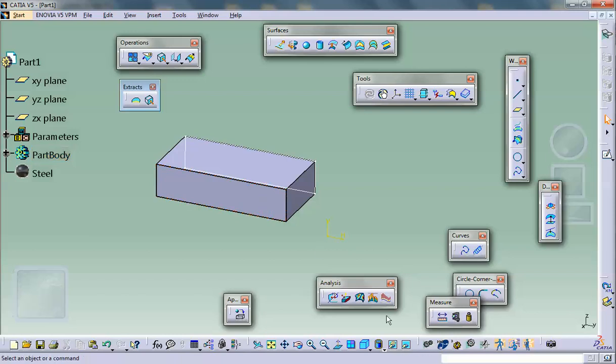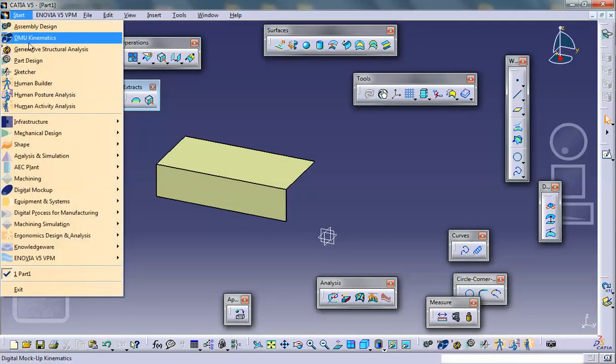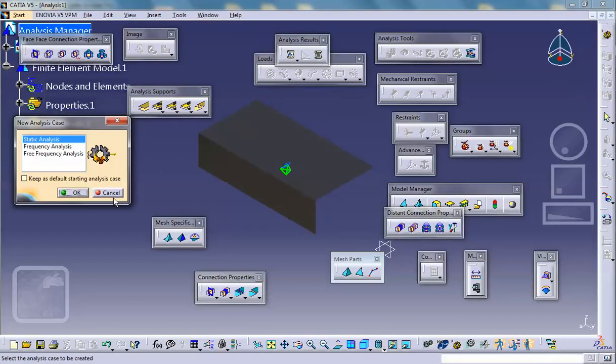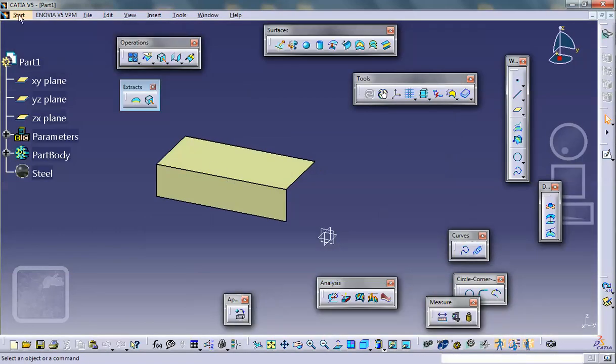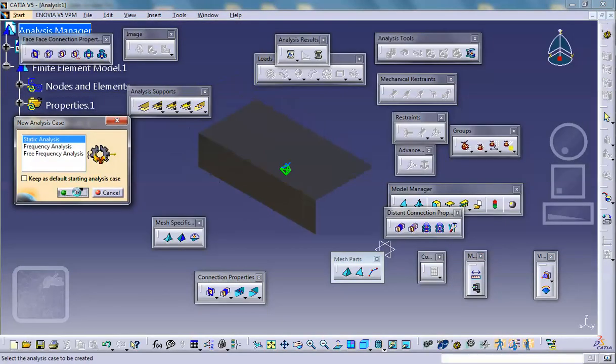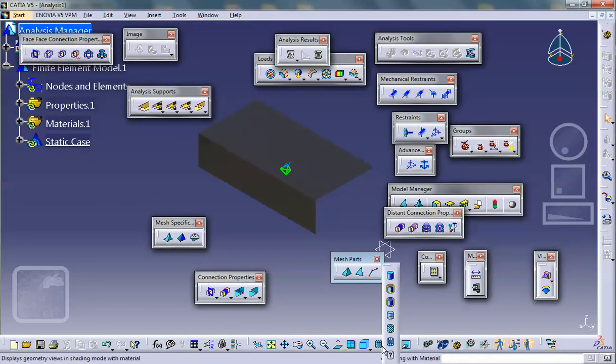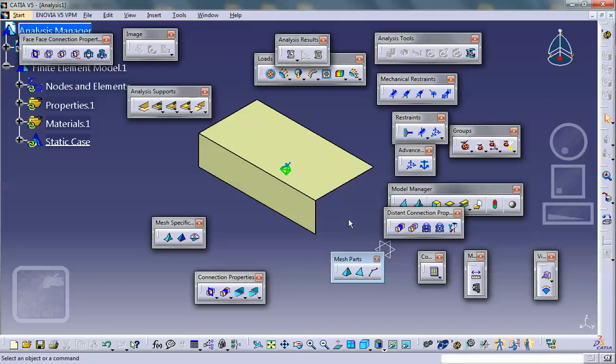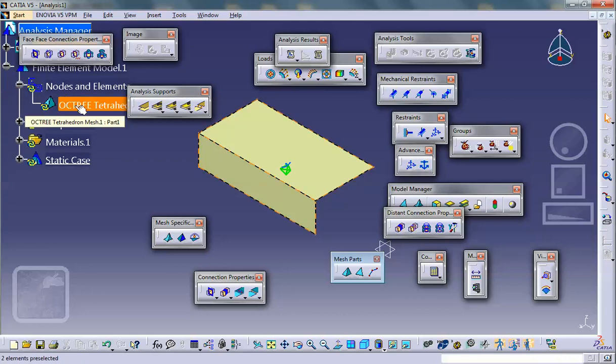Immediately, you see that the box that's in hiding is meshed with solid elements. Here are solid elements. We don't want these elements because we're supposed to do this problem with shell elements. And also keep in mind that if, on a test, you are asked to use the best element to do this problem, and you use solid elements to do that, basically you ignore an instruction, you get no part marks. Okay, so I'm going to have to delete this element. We don't need it. And also a 3D property was automatically created, so I have to delete this one too.